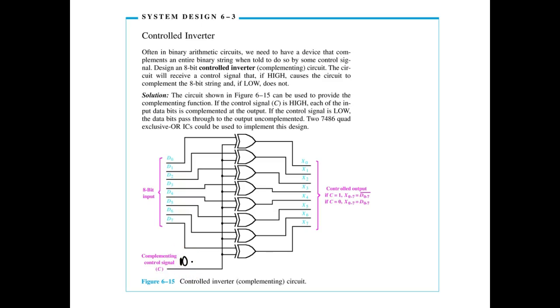And this is what we had on our video. This is all we had on that video part. It just had a bunch of exclusive ORs. I can show y'all the schematic later on. They're in that big blue book, and you'll see that switch. We flip a switch, and it would let the horizontal sync come through as a positive pulse. If I flipped it, it would convert it over to a negative. So we can use them as what the book calls controlled inverters. Technically, they're not always inverters. We're going to make them inverters or we're going to make them act like buffers, right?